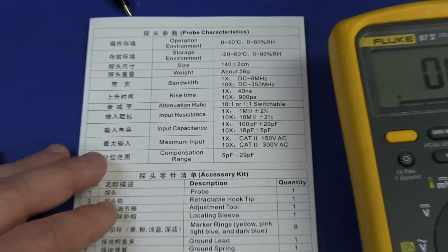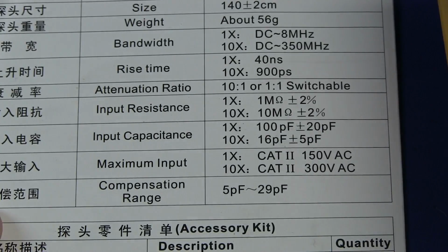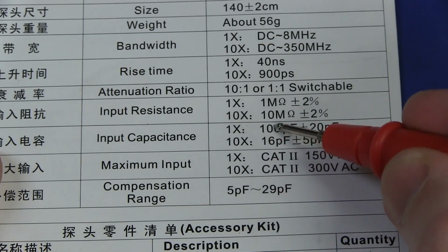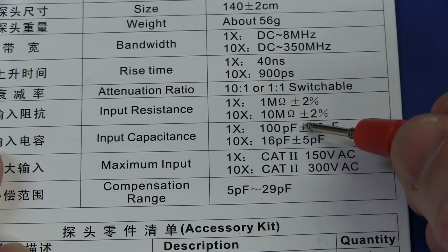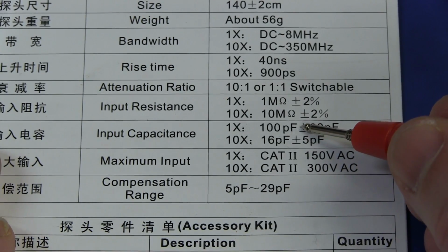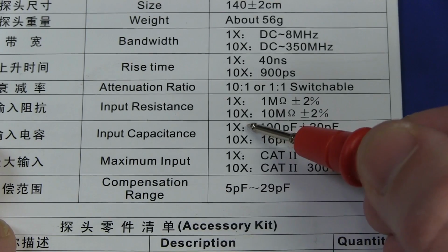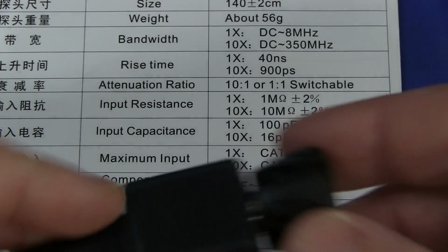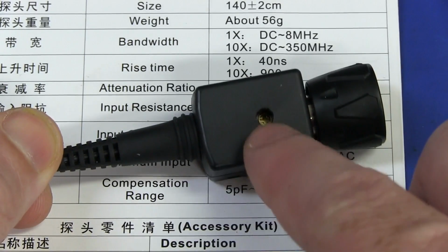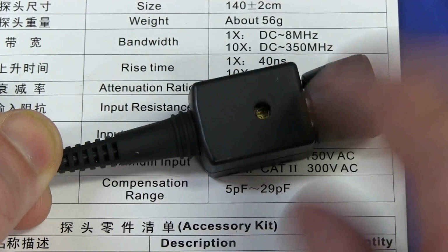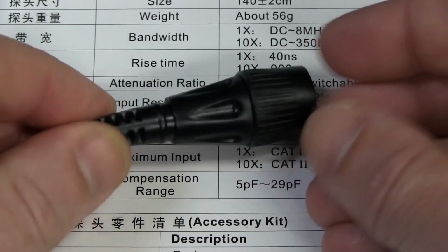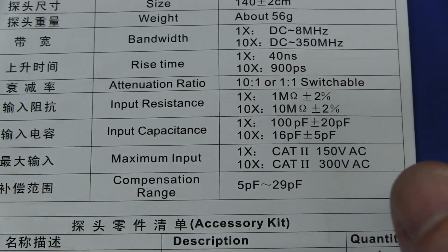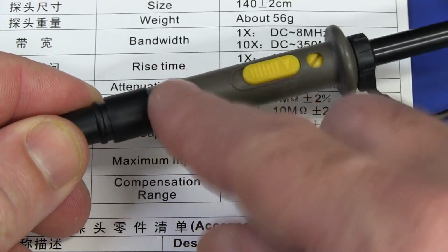Now before we get to the multimeter, let's just have a look at the input specs again and see how they relate to what we've seen on the whiteboard. Let's look at the input capacitance here in ×1 mode, 100 picofarads. Now that's effectively the capacitance of your coax cable only, because the ×1 switch of course shorts out the input compensation network and all you're left with is the coax. But it can actually also include the compensation network if you've got it at the end of the cable like here, at the scope end, rather than this one here, which just has the coax going directly into the scope. And in that case, they'll have the compensation network up here.